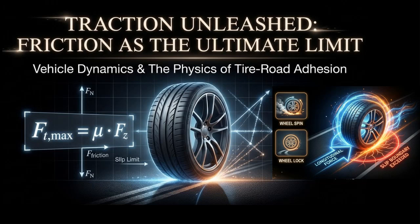Traction comes from friction between the tire and the road. When engine or brake torque is applied to a wheel, the tire pushes on the road. The road responds with a friction force that moves the vehicle forward or slows it down. This friction force is responsible for every acceleration and every controlled stop.